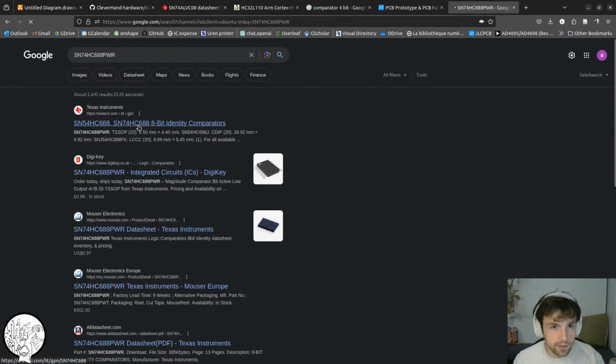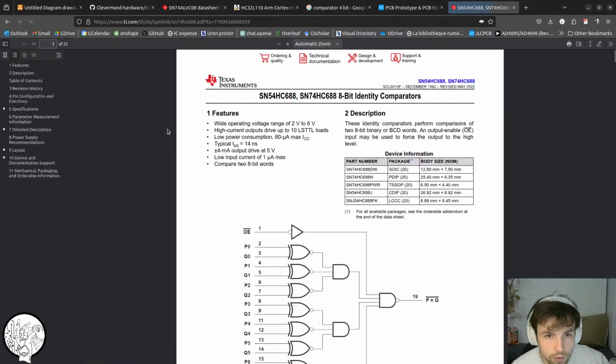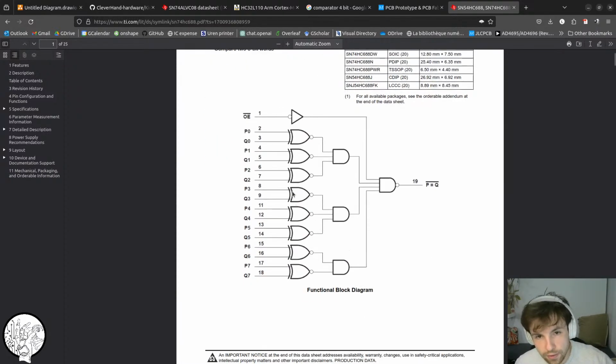And when you look at it, what is nice is it's 8 bits, so that means that we could maybe extend it to more than 16 addresses. And this is exactly what it is doing. Every Q pin would be connected to the microcontroller and predetermined at the beginning, at initialization.